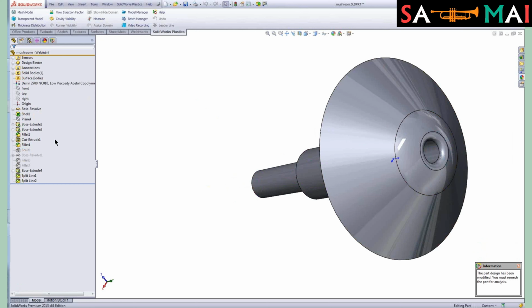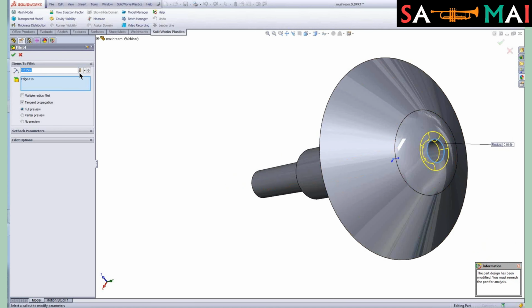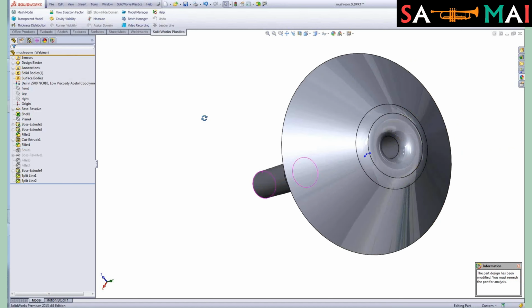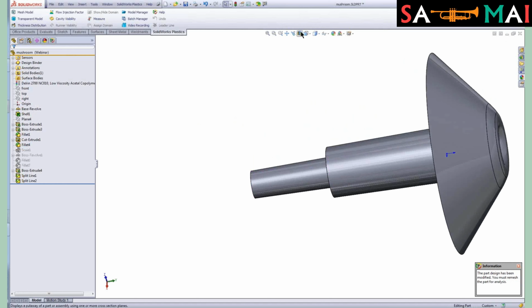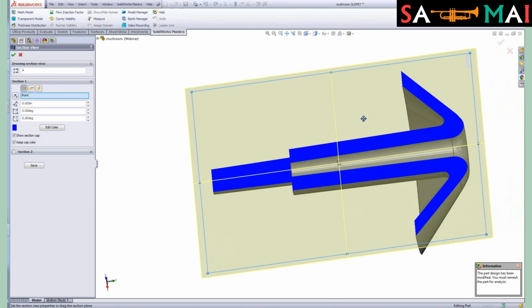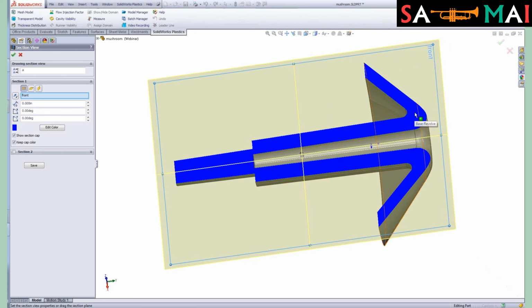So let's go in, change our SolidWorks model where we're going to change the value of this fillet. So it was 15 thousandths of an inch. Let's make it 35 thousandths of an inch for our design change. So you can see that that really changed that cross-section right at the end there of this particular part.